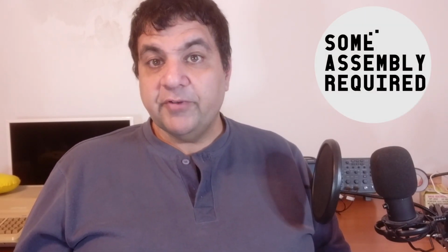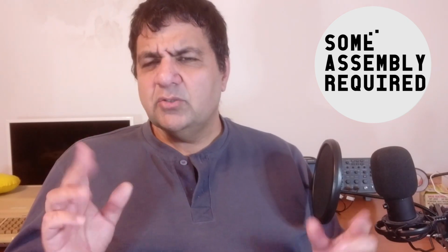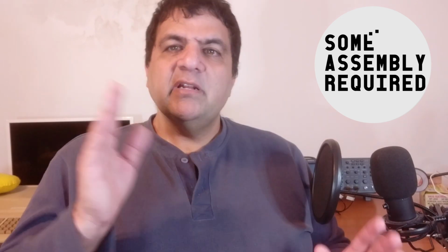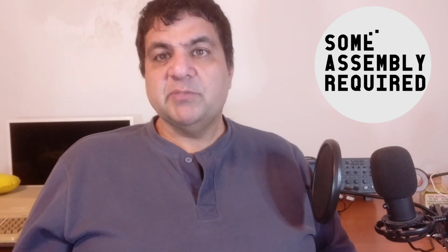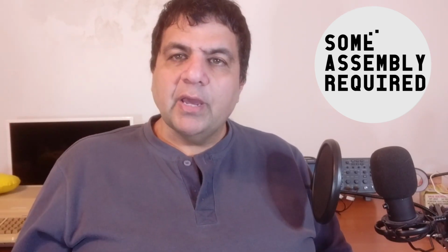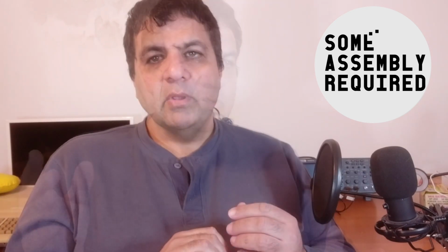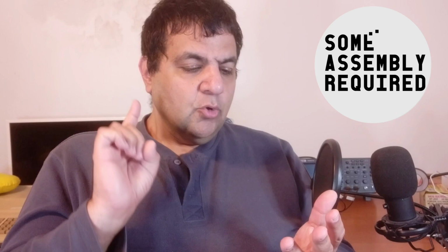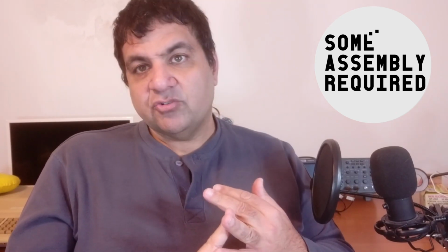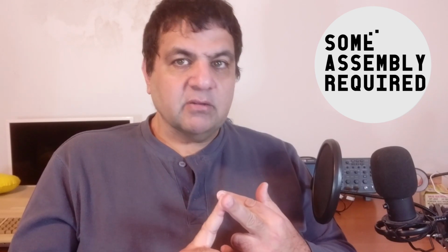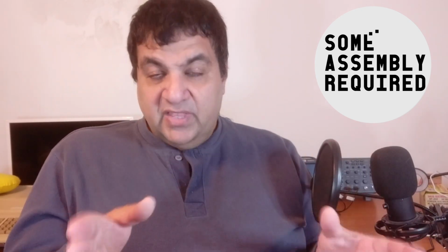In this video we will finally be implementing an opcode. The video itself turned out a little too long, about 1 hour, so I split it up into 3 parts. The first part, the part you're watching right now, is all about preparing the implementation. So we collect the data we need, we match it up against the actual 6502, and we create the test bench test plan. That's this video.